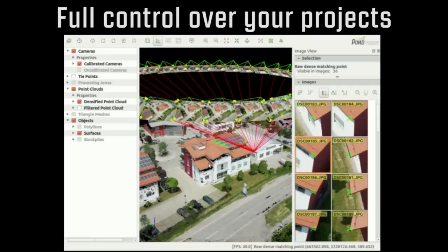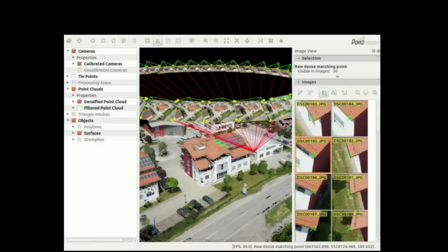You can introduce very nicely ground control points or manual tie points in order to get a better accuracy on the camera centers. For this we are using a strictly multi-ray approach. So we are not only using 2 images as in traditional photogrammetry to estimate the 3D location of a certain point, but we are using all available images with this editor. Why is this important? This is what I show you in these slides.